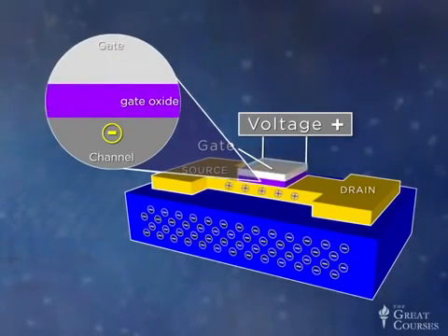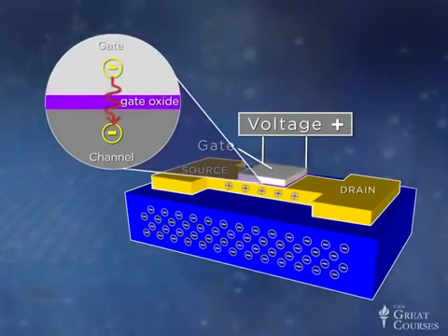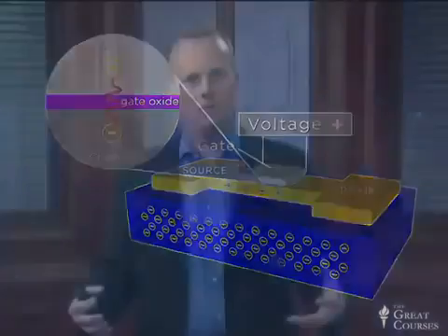Now, the thing that we loved so much about this transistor model, in which essentially no current flowed into our channel, is that we got a huge leverage in our switching. It cost us almost no current to switch a very large current. Now that advantage is compromised through tunneling. So this is an example of where quantum mechanics, if we don't change our paradigm, if we don't change our approach, starts to imperil the advantages of silicon electronics.